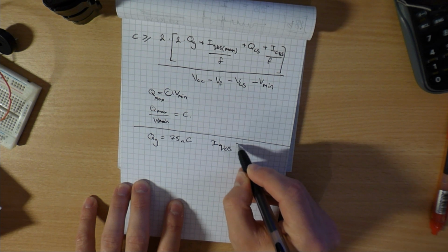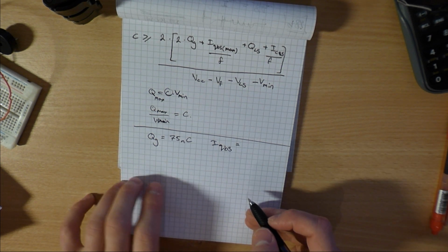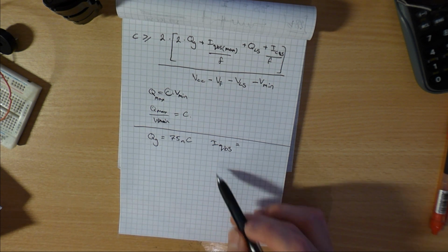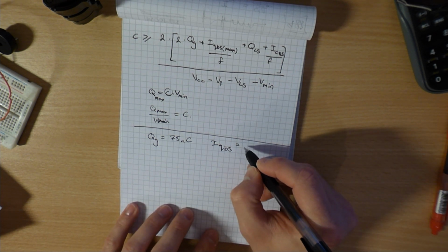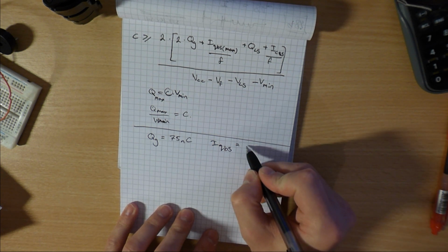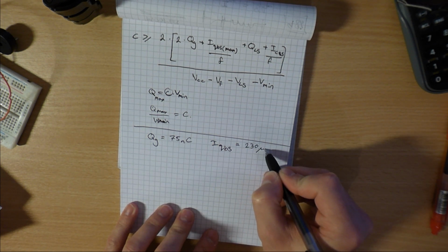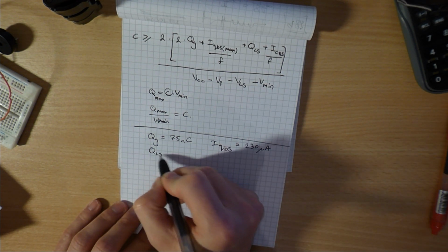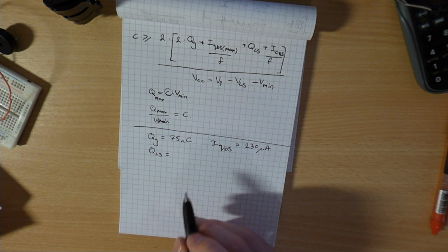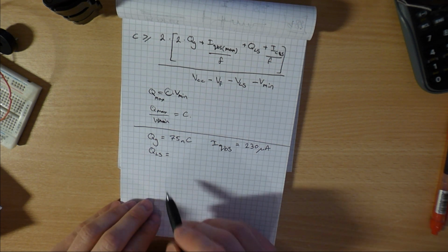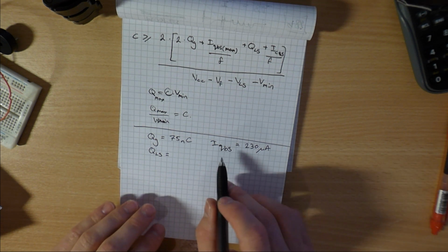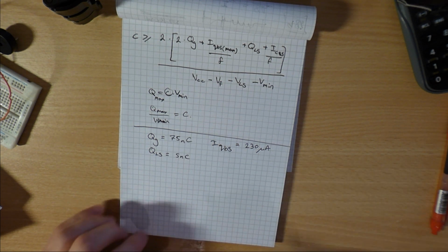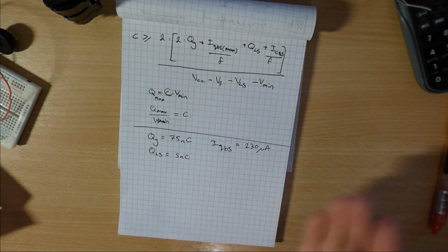IQBS is, I think, the quiescent bootstrap capacitor current, which is an attribute associated to the IR2110, so you can look that up in the datasheet, which is 230 microamps. QLS is the level shifting charge required. Again, that's an attribute of your driver, so it's typically 5 nanocoulombs for a 5 to 600